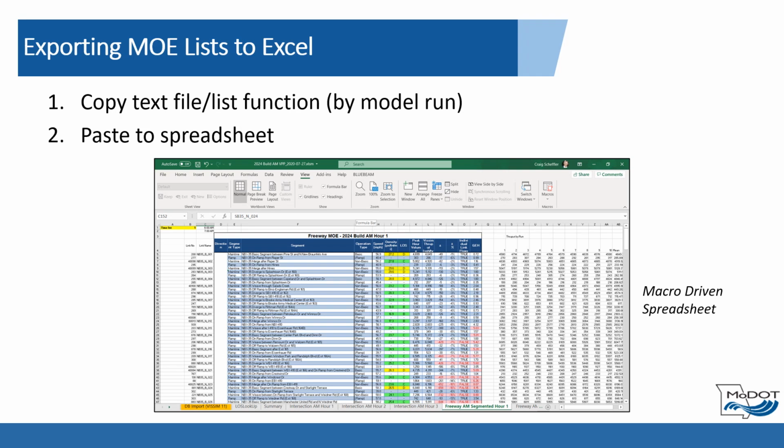One common MOE, level of service, is produced internally by Vissim in the node evaluation file. If level of service output is desired for other situations involving, for example, freeway segments, then post-processing of appropriately matching sections of the freeway in the Vissim model to HCM criteria will be necessary.